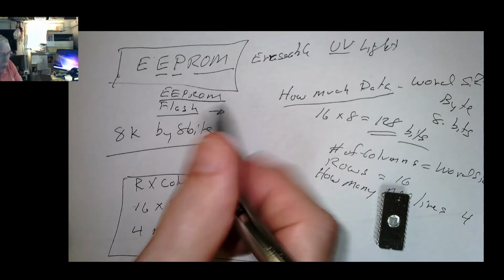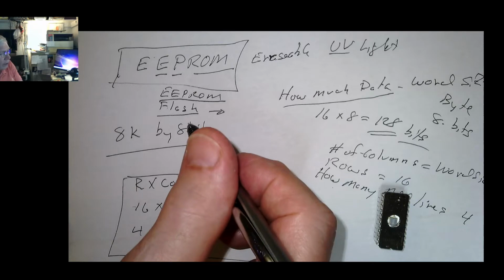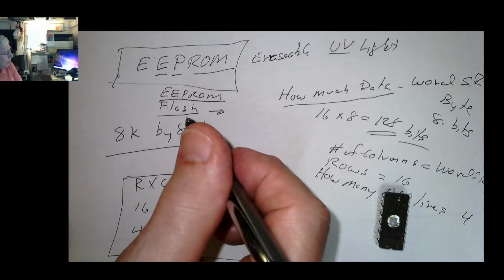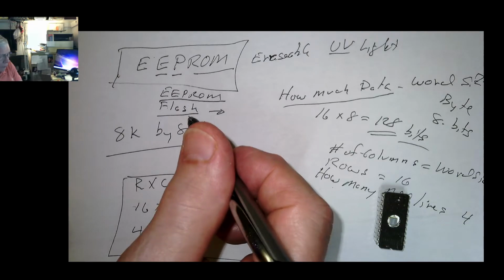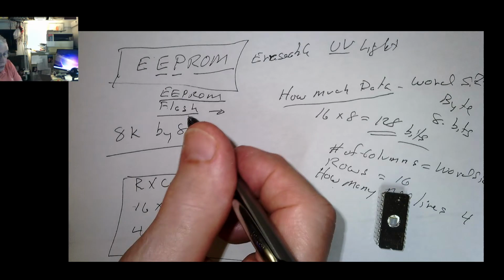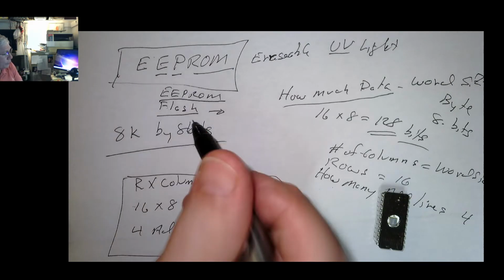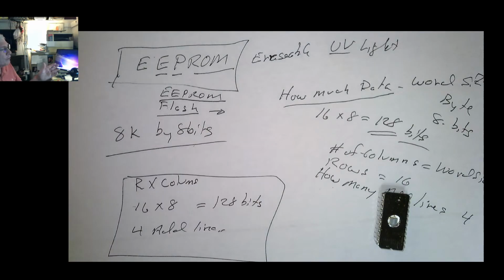EEPROM has a little bit longer life. Flash definitely wears out, and if you use it many times, maybe 100,000 erases and reads and writes, you will wear it out. So all of your jump drives have special circuitry to try and evenly distribute the usage across the entire flash memory inside that jump drive. And it's the same thing with solid state drives. They're just flash memory, and they have the same kind of management software or hardware to make it work. Okay, so let me go back.